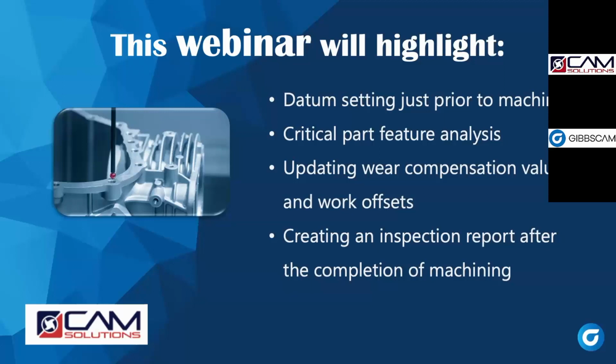Most people have a probe lurking in their CNC machine somewhere in the tool changer, and they bring it out every once in a while to find the corner or to find the bore of a part. But if you could do that automatically inside of GibbsCAM and be able to control your program with the door closed and have the probe automatically update your wear comp offsets and automatically set your datums, you will find a tremendous benefit. We're going to talk about those benefits.